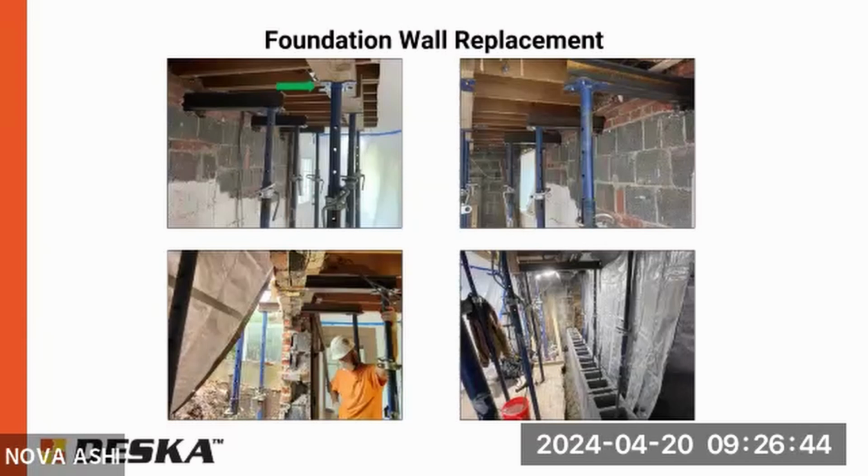So what has to be done is, before the wall can be removed, what we call needle beams need to be installed through the wall at certain spacing to support the heavy wall above it. You'll see there's a column and you have a beam that goes through the wall. There's a column on the other side of that wall as well. And if you look at the exterior picture here, you can see where the wall is completely removed and solely the needle beams are supporting it until the new wall can be built.